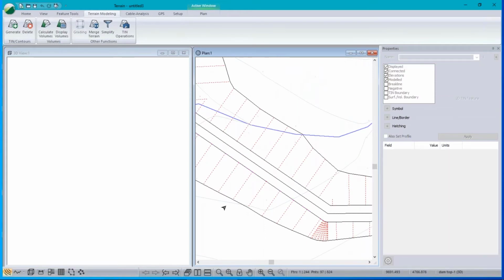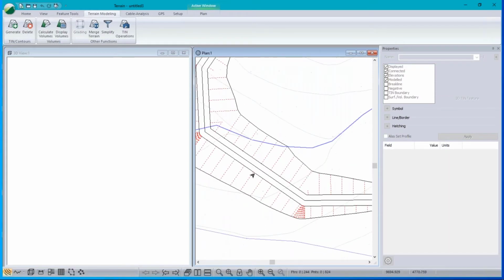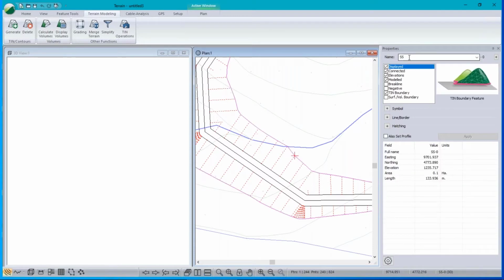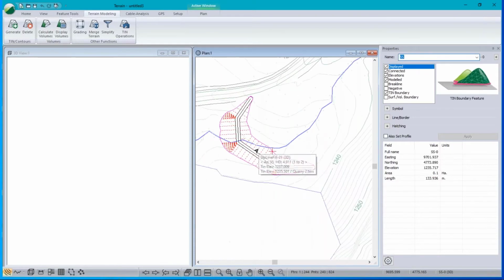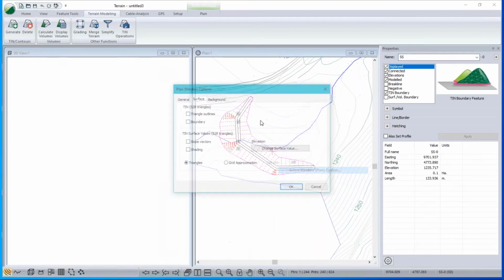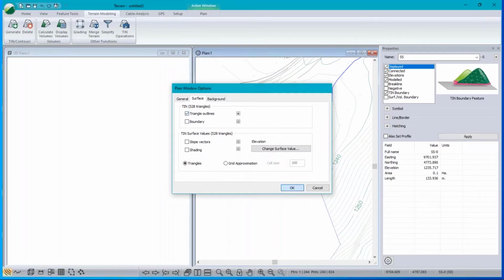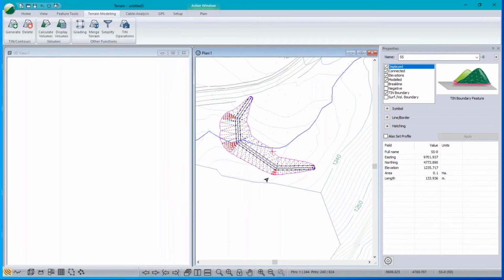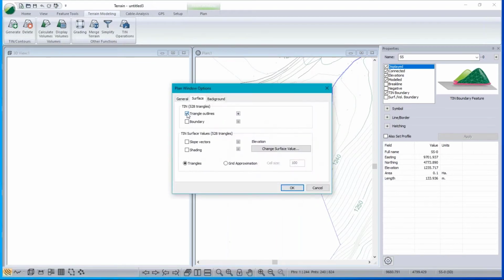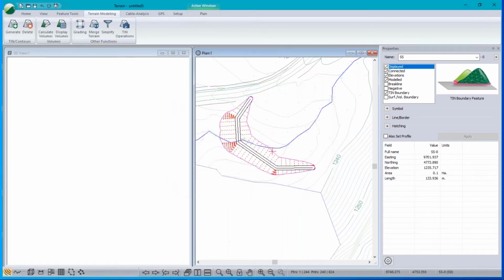These are called slope lines. What it's doing is it's grading down until it hits the surface, and then it's connecting up all the dots to make this thing called a surface polygon boundary. That is set to a tin boundary, so there's no triangles outside of it. The surface is contained within that boundary. And I've got a good volume.